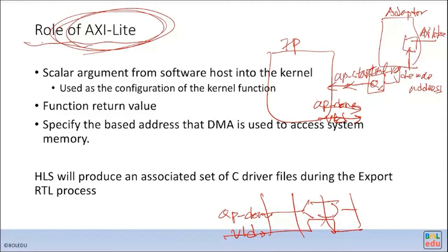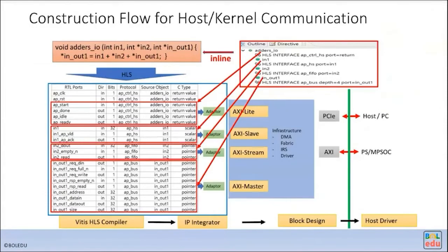So for the design, it becomes a register, and the register has an enable signal and a clock. The enable is driven by the valid signal, and the data input is the AP done. This signal can then be read out using the AXI Lite protocol, read to the host program. Understand? Later I will use a slide to show the whole picture and put everything together.